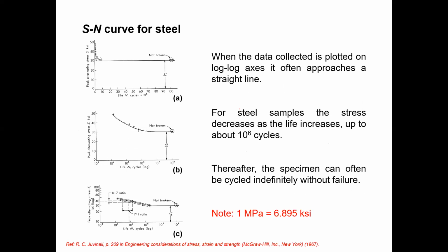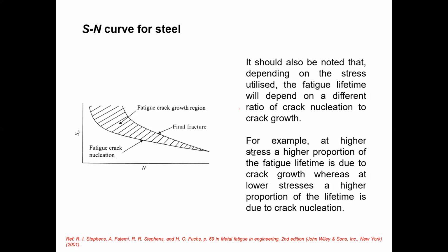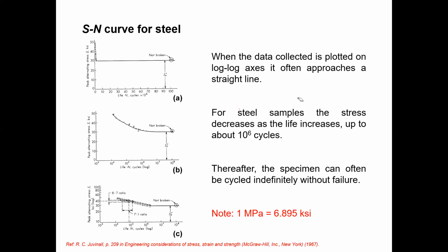This is the saturation, the endurance limit: after some time it saturates and strength does not reduce more, even if you apply more cycles. If it is going to break, it breaks somewhere here; after this point it will not break. So you need to expand this area.